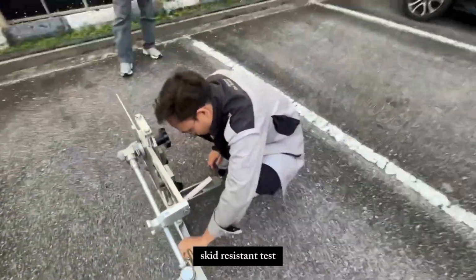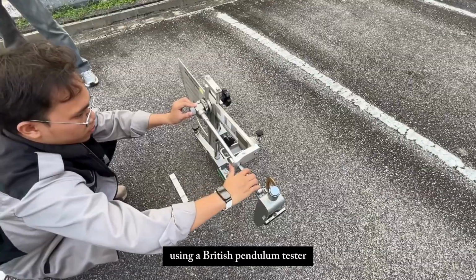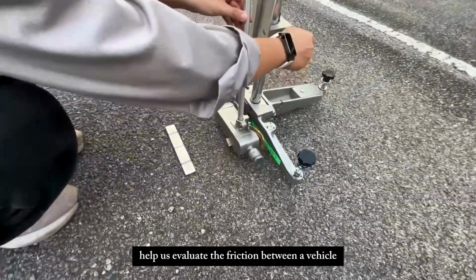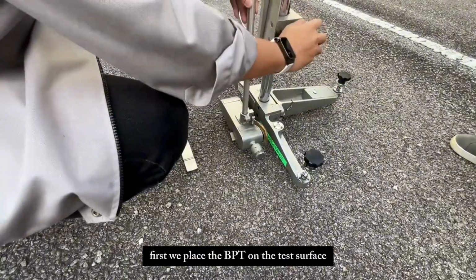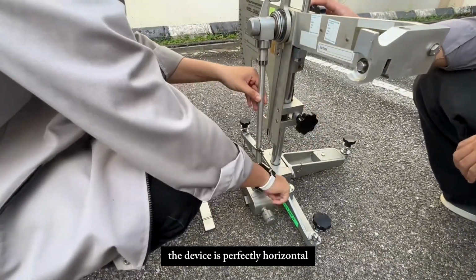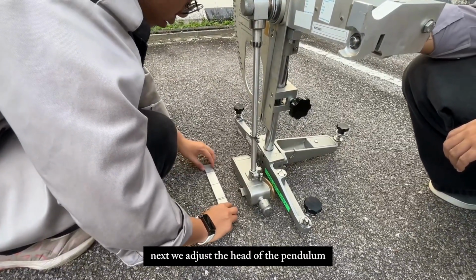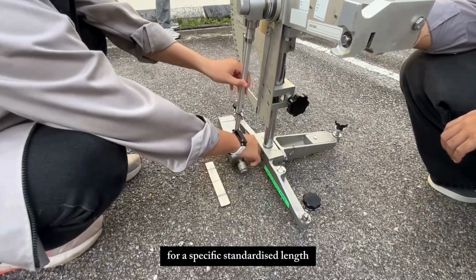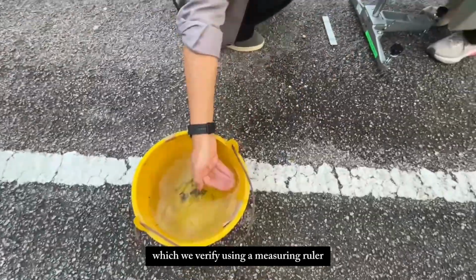Skid resistance test. Our first test measures skid resistance using a British pendulum tester or BPT. This test helps us evaluate the friction between a vehicle's tires and the road surface. First, we place the BPT on the test surface and use the built-in spirit levels to ensure the device is perfectly horizontal. Next, we adjust the height of the pendulum so that the rubber slider contacts the pavement for a specific standardized length, which we verify using a measuring ruler.